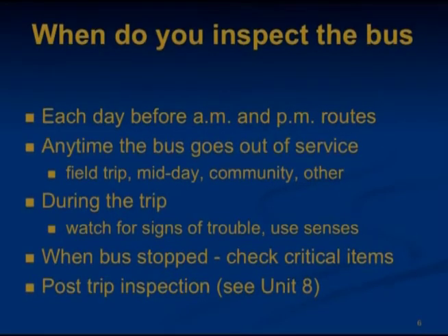Look, listen, smell, feel. The transmission shouldn't be making unusual noise. It should have a smooth response to the accelerator, should not be skipping, and there shouldn't be any metallic grinding sound. The engine, be alert to unusual noise, vibrations, or the lack of a normal response. Never race a cold engine. Check the speedometer and tachometer. Make sure they register correctly.